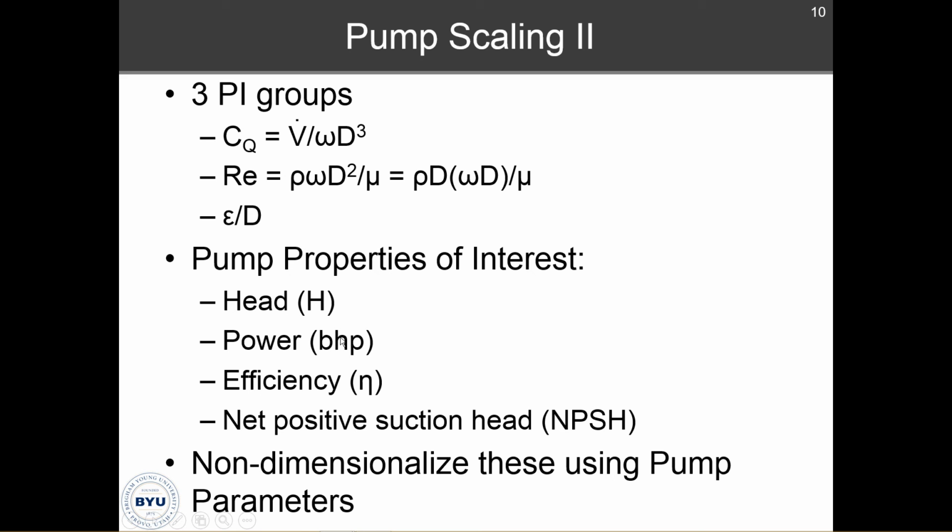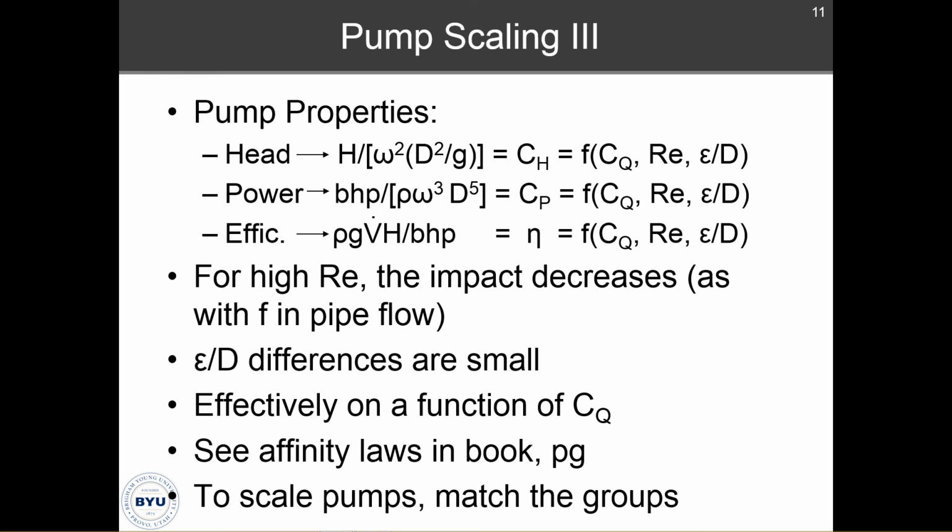So what we're going to do is non-dimensionalize these parameters, because these are the ones that are of interest to us, using the pump parameters. Okay? So we take the head and apply the different parameters to non-dimensionalize the head. What we end up with is the coefficient of head, and that is a function of the coefficient of flow, the Reynolds number, and epsilon over d.